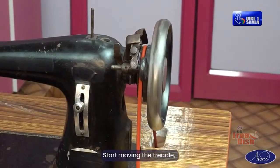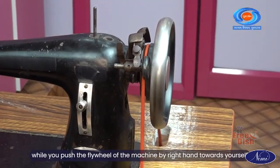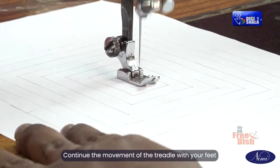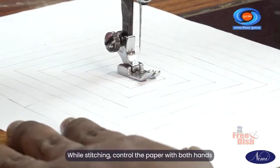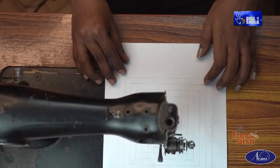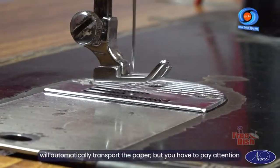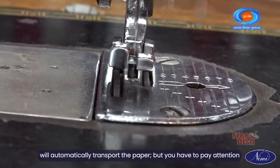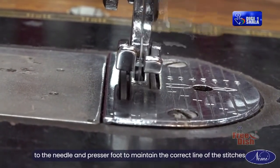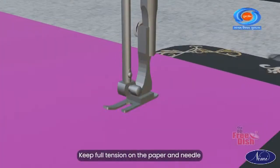Start moving the treadle while you push the flywheel of the machine by right hand towards yourself. Continue the movement of the treadle with your feet. While stitching, control the paper with both hands. With the movement of the machine, the feed dog will automatically transport the paper, but you have to pay attention to the needle and presser foot to maintain the correct line of the stitches. Keep full tension on the paper and needle.